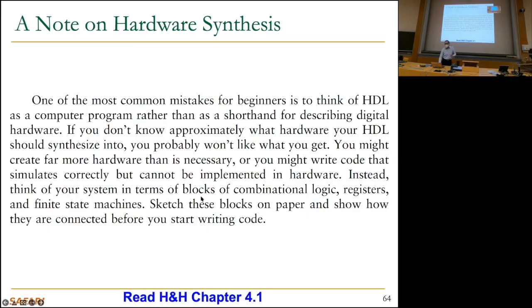Instead, think of your system as blocks of combinational logic, registers, and finite state machines. That's the best way of thinking in hardware, actually. Sketch these blocks on paper and show how they are connected before you start writing code. And this is actually very good advice, because sketching things is easy if you use hierarchical design principles also.